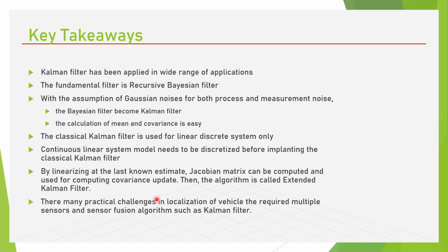In modern navigation systems, for a mobile robot or a self-driving car, they use encoders and cameras, which can be interpreted via image processing and then kinematics. Then we can compute the velocity of the vehicle, and from the wheel encoder or tachometer we can also compute the velocity of the vehicle, and then we can fuse them to have a better estimate of localization.